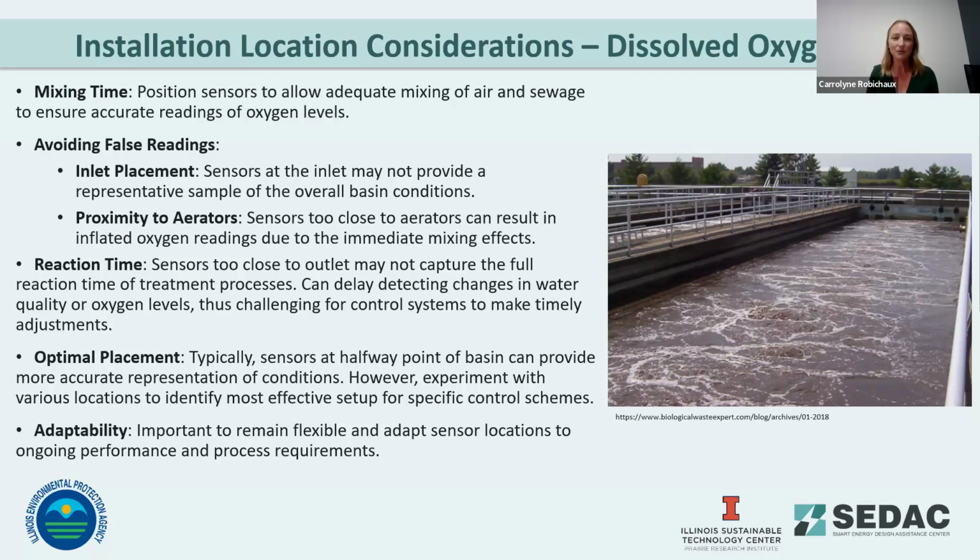Now, a lot of these sensors do have fairly long cabling. I would say the standard cable length is 30 feet. So if you have an 8-foot dip pull, you have plenty of room without moving the controller that's mounted on the handrail. You have plenty of room to move up and down that DO sensor before you have to physically move the controller and the electrical work itself. And so that goes right into adaptability: give yourself some time. Don't stress if it's not quite right at startup.